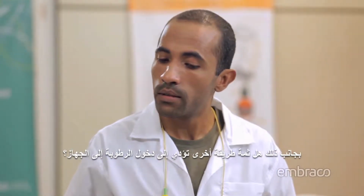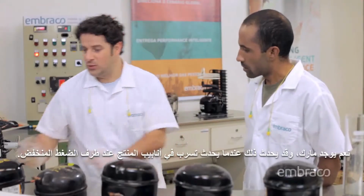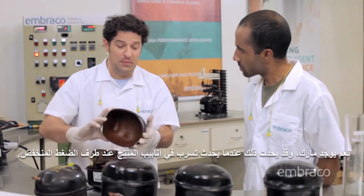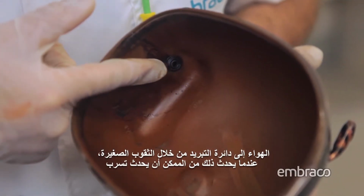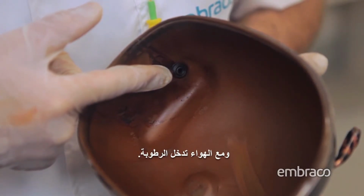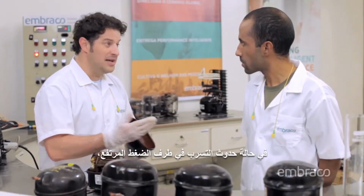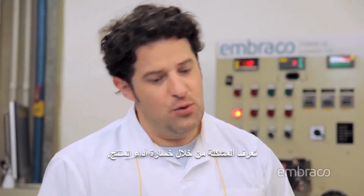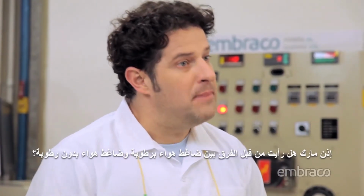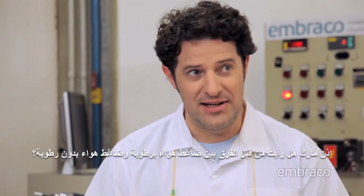Oh, besides these, is there any other way for moisture to get inside the compressor? Yes, there is, Mark, and this might happen with leakage in the product's tubing on the low-pressure side. When this happens, it's possible that air infiltration occurs in the cooling circuit through micro holes, and together with the air comes moisture. If leakage occurs in the high pressure end, the problem will be identified with the loss of product performance. So Mark, have you ever seen the difference between a compressor with moisture and a compressor without moisture?